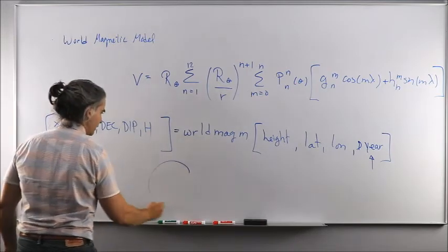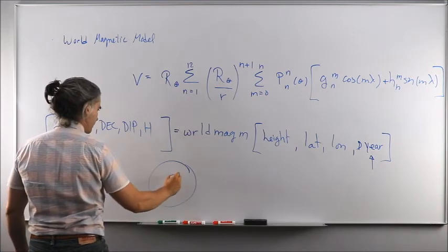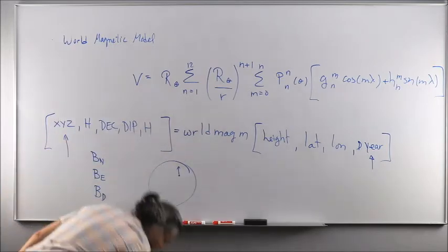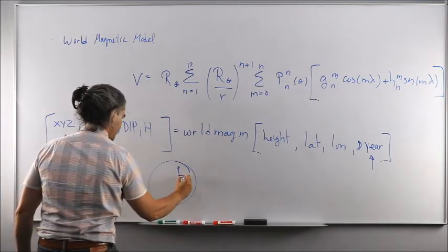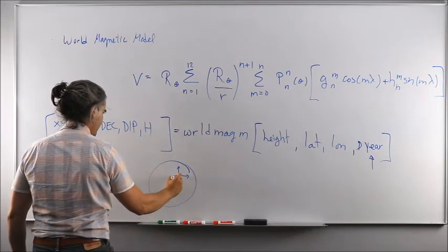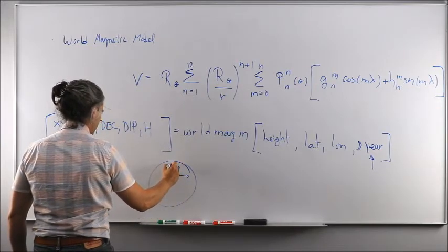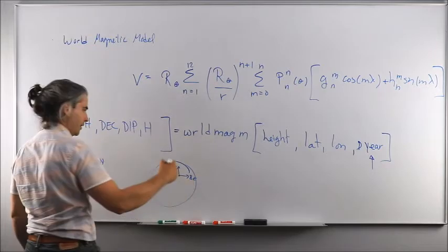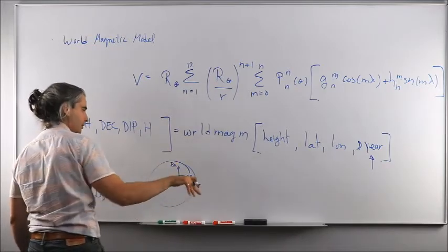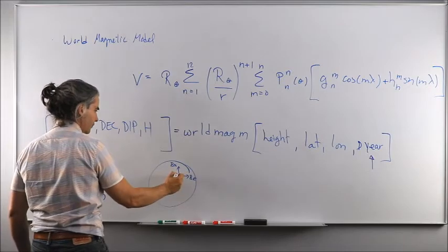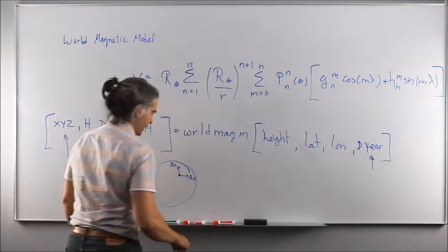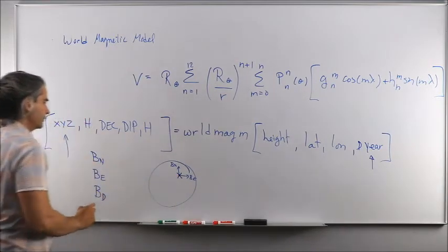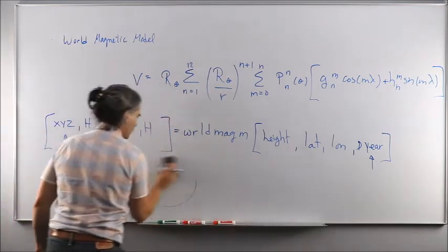So if you have, say, the Earth, that reference frame would have its X unit vector pointing towards the north. Its Y unit vector pointing towards east. And so that would be in the direction of east. And down would be cross product of X and Y of NED, so coming towards the Earth, or down, okay, looking down at the Earth. Like that. All right? So, it's easy, right?